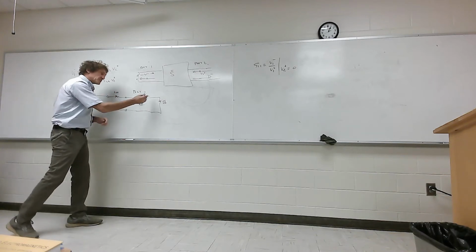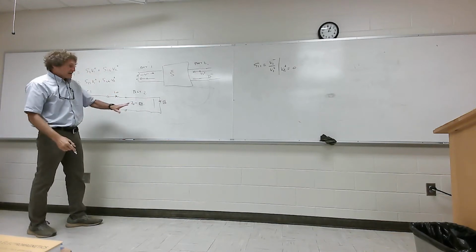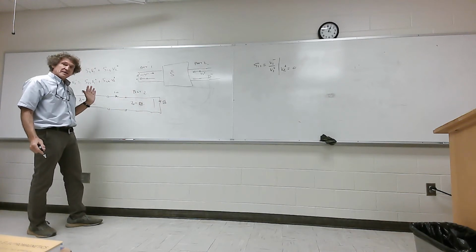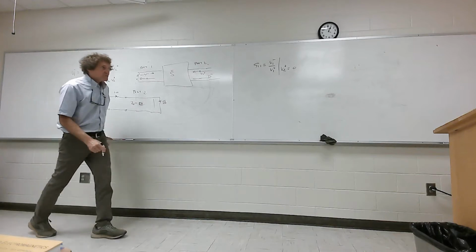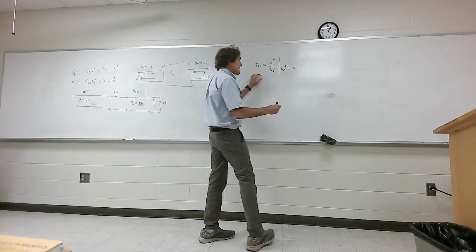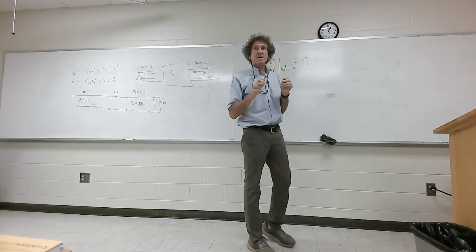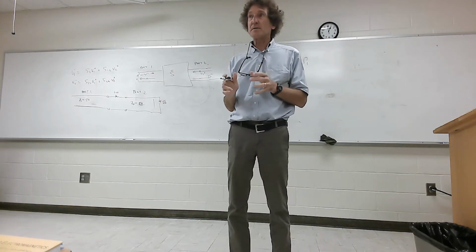If it was a short circuit, you couldn't do it that way. It has to be into a match condition, so V2 plus, there is no reflected wave back into the port. You all with me? All right, so for this one, if that is the case, this is really just the reflection coefficient of port 1, assuming it's matched. You all follow me on the thoughts on it?